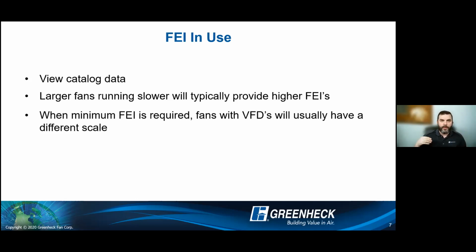So if you're without a VFD, the statement might be you must meet a minimum FEI of 1.2. And then it says applications where VFDs are applied, minimum is 1.0 or 0.98. So look for those statements and the different scales when they're used.